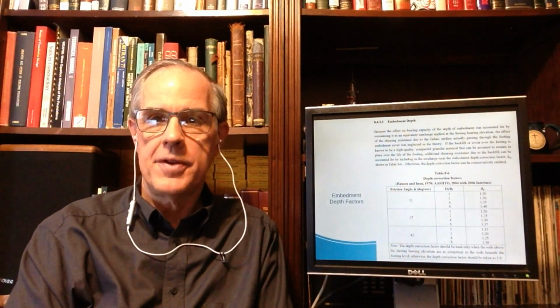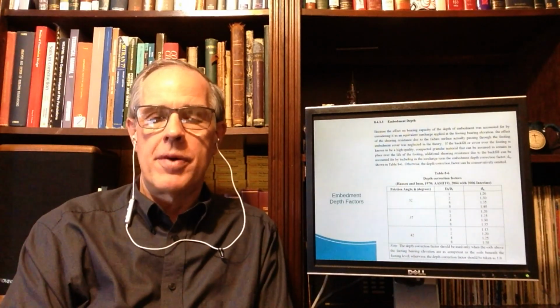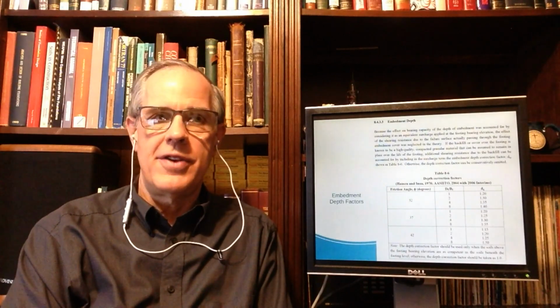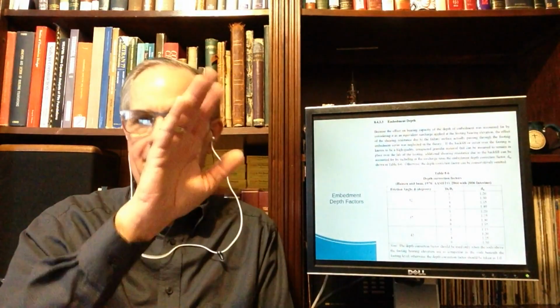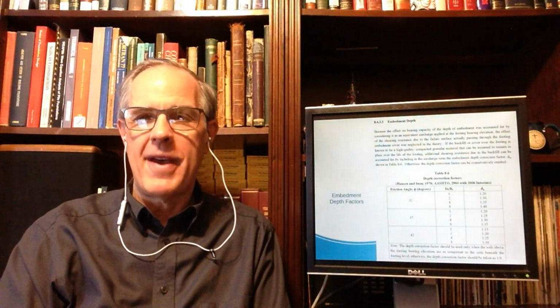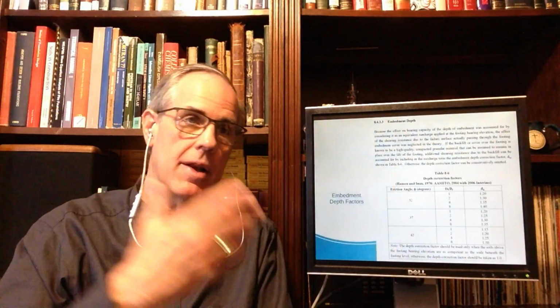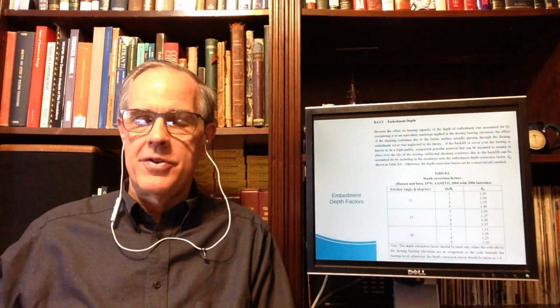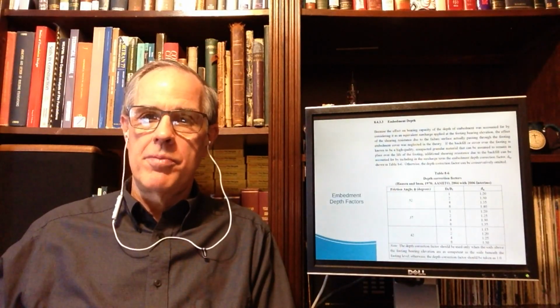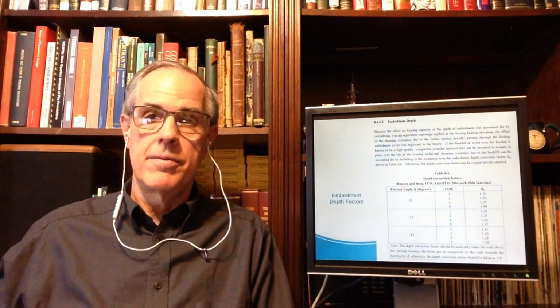And to be honest, this has been a subject of debate. The problem with the embedment depth factor is that, generally speaking, when you put the foundation in, you backfill it. The quality of the backfilling can be dicey. They may not compact it. The best thing to do is not to include it in the bearing capacity factor. So for this course, somebody might tell you to include embedment. I won't. I don't think it should be included, and there are other researchers that don't either.